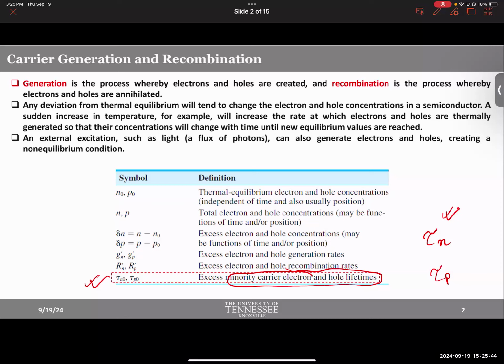How many of you heard about solar cells? All of you, right? The biggest challenge in solar cell that engineers try to tackle is how to separate generation and recombination. So when you shed light, non-equilibrium. Solar cell is nothing but a p-n junction. Simple. You have p-type and n-type semiconductor side by side. When light comes, it generates carrier, extra carrier, electrons and holes created. If you could somehow separate them out before they recombine and destroy each other, there you go. You charge up the battery. But if you don't, if you set a solar cell and light comes in, it will keep creating electrons and holes forever, but you cannot charge anything because after a certain amount of time, it will recombine and cancel each other out.